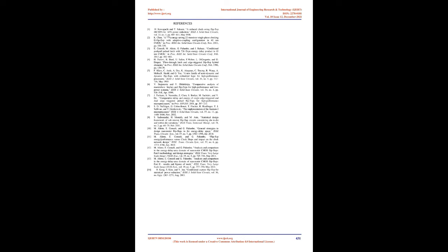The 2 pulses are generated by a local pulse generator to avoid pulse distortions from additional pulse buffers and wiring. The pulse generator can be shared by a few neighboring flip-flops to reduce pulse generator area and energy overheads. This DPSCRFF does not allow arbitrary time borrowing across the transparency window as with other pulsed latches. Time borrowing is only possible for late arriving high inputs, e.g., from a preceding domino logic stage or a preceding skewed static logic stage.